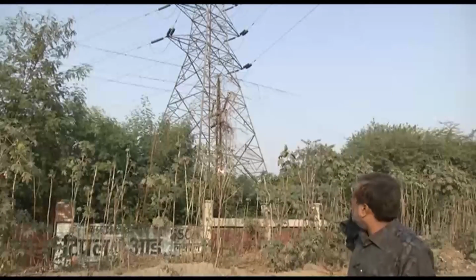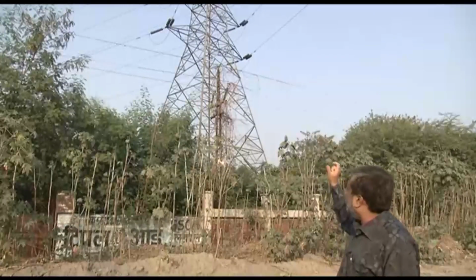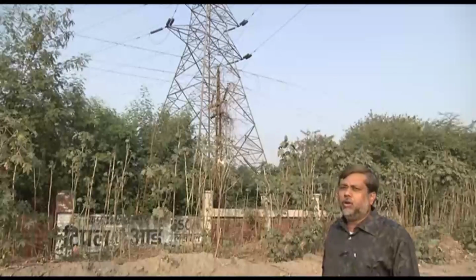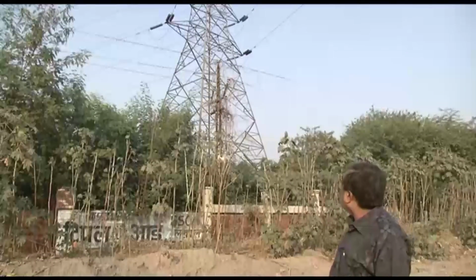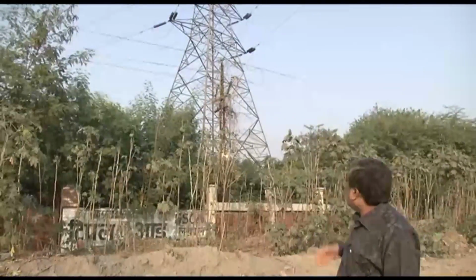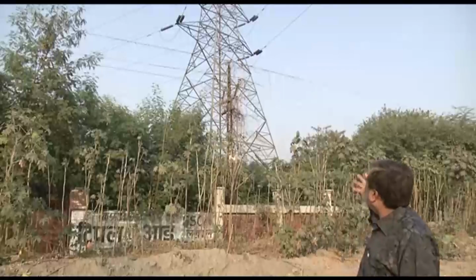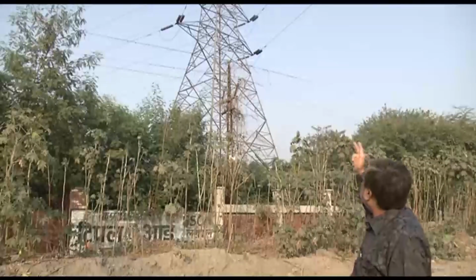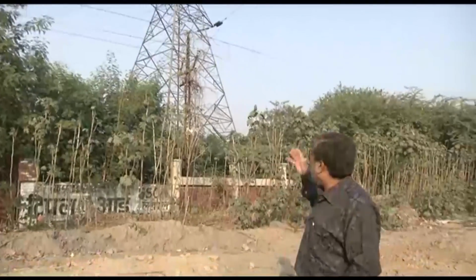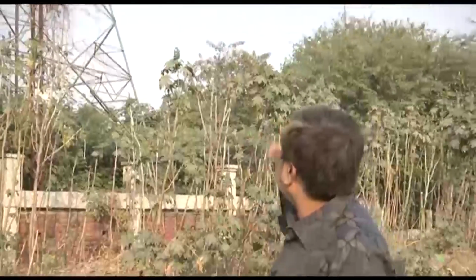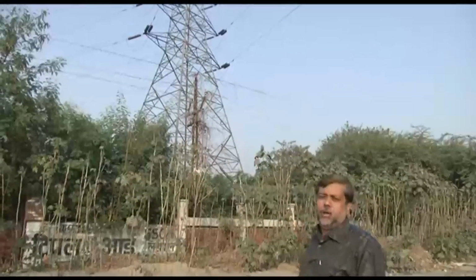Now this Stockbridge damper, which essentially has two additional masses hanging from the power line with the help of a messenger cable, works exactly like the tuned mass damper that I have shown you in the laboratory, and this tuned mass damper system absorbs this Aeolian vibration, the vortex induced vibration of these wires, and keeps these wires very steady so that they do not give up, and as a result a continuous power supply is possible in the system. So this is a fantastic application of vibration control with the help of a tuned mass damper system.